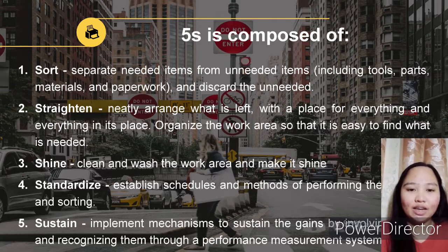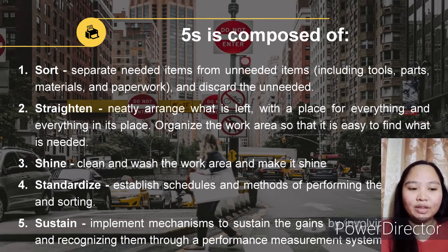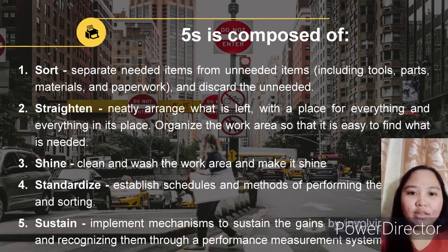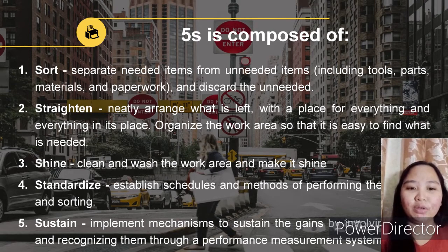The first S stands for sort. It means eliminate whatever is not needed by separating tools, parts, and instructions from unneeded materials. The second S stands for straighten. It means organize whatever remains by neatly arranging and identifying parts and tools for ease of use. The third S stands for shine. Clean and wash the work area and make it shine. Working in a clean environment enables workers to notice malfunctions in equipment such as leaks, vibration, and misalignments.